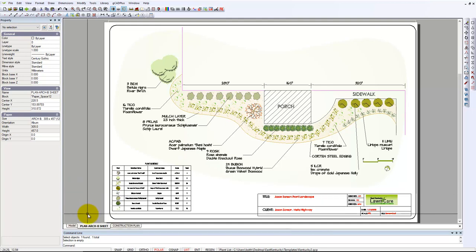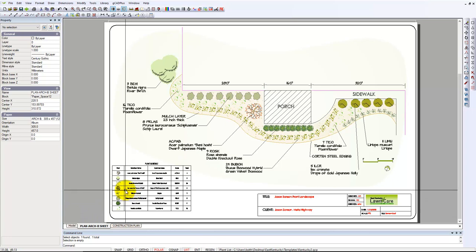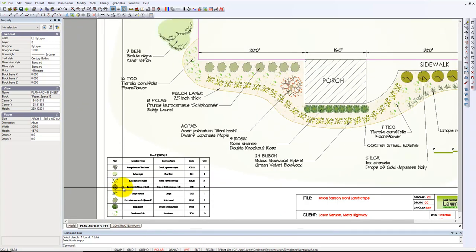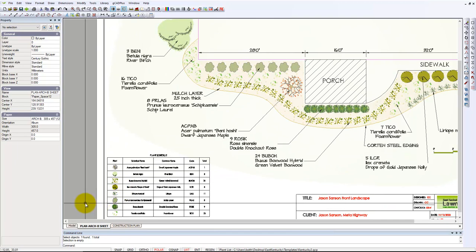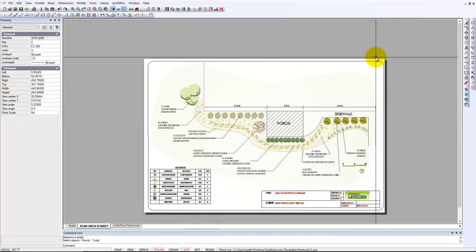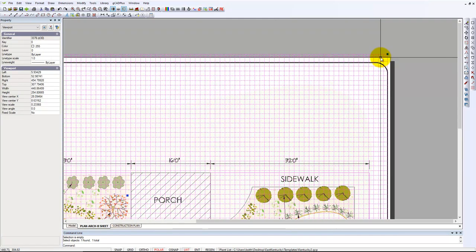The other thing you may have to watch, although it's been set correctly here, don't forget that you can control visibility within a floating viewport. Let me come back here again. I'll select that floating viewport, which we now know controls the whole design.